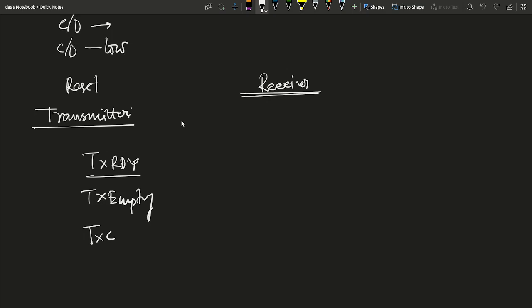Third, when the RxD line goes low, the control logic assumes it is a start bit and waits for half a bit time and samples the line again. Next, if the line is still low, then the input register accepts the following bits, forms a character and loads it into the buffer register.